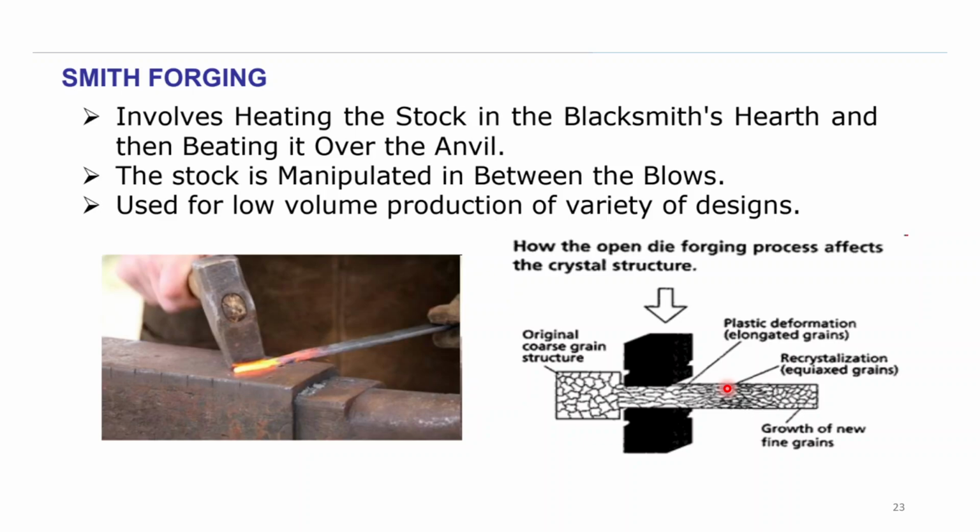The elongated grains will reduce the strength. It won't, but it will provide you anisotropic behavior. If you are comparing it to a coarser grain structure, then compared to that it will have better strength properties. But if you are comparing it to a very fine grain size, then compared to that it will have inferior properties. So it depends on what you are comparing it with.